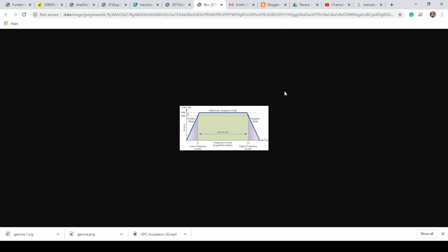The most important thing when you study an amplifier, for example, if I'm designing it for audio frequency, is the maximum gain. At what frequency, and at how much amplitude of gain, do I get? At very low frequencies, I would not be able to get great gains. At very high frequencies, I will not be able to get great gains. But in a frequency range between particular values, I'll be able to have moderate or almost uniform gain. That's a desirable performance. And this band is called the bandwidth.